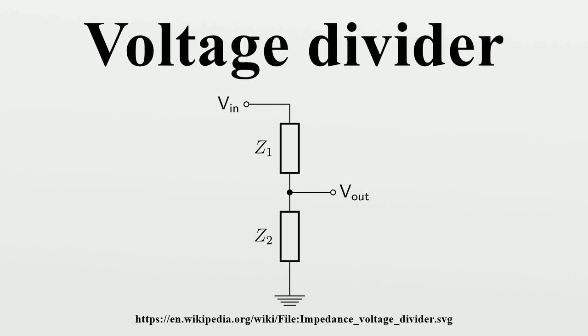Sensor measurement. Voltage dividers can be used to allow a microcontroller to measure the resistance of a sensor. The sensor is wired in series with a known resistance to form a voltage divider, and a known voltage is applied across the divider. The microcontroller's analog-to-digital converter is connected to the center tap of the divider so that it can measure the tap voltage and, by using the measured voltage and the known resistance and voltage, compute the sensor resistance.